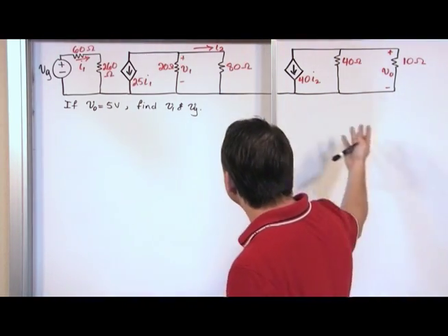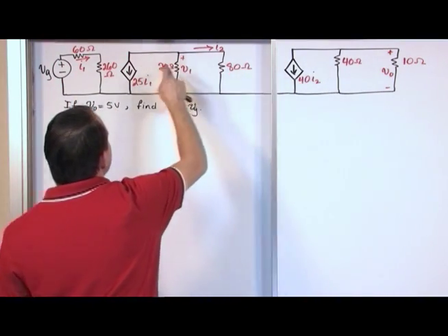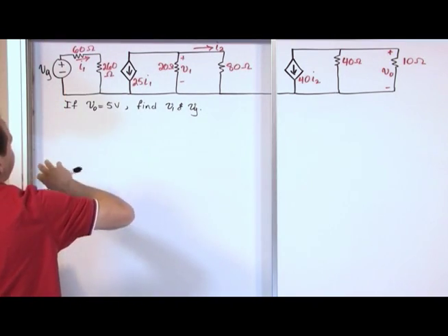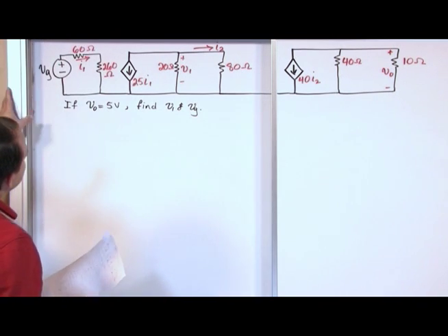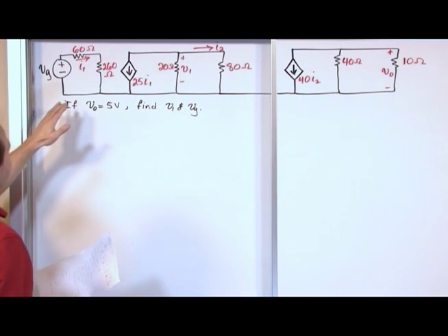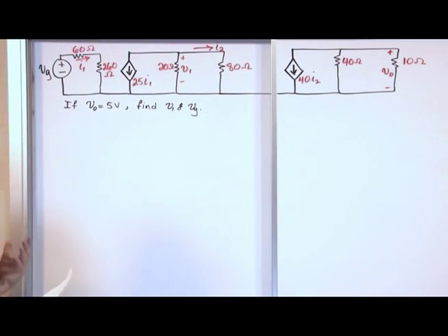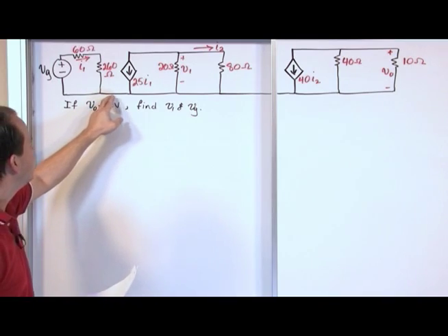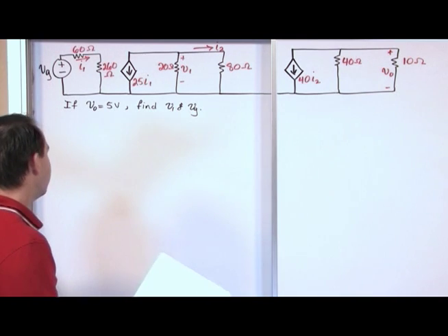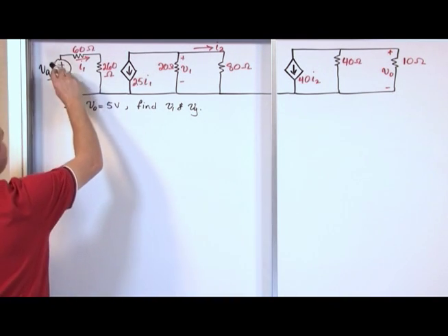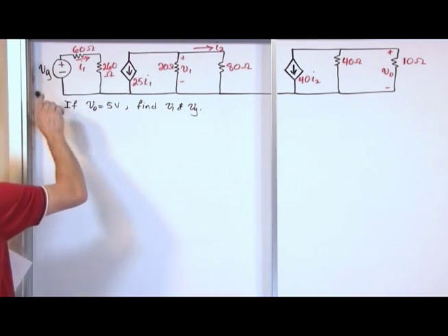So that's what is sort of trying to be illustrated here. You've got a circuit here, you've got a circuit here, and you've got a circuit here. These sources are really dependent on what's going on over here, but we've tied their low sides together so that the low side of their voltage between each of these circuits really is at the same place. So if you ever see a circuit like that that's got something tied together at the bottom, that's all that's really happening. This is what I thought when I first saw this years and years ago: it doesn't mean that you've got current from this source going through this and doing something nuts and coming back. That's not what it means.